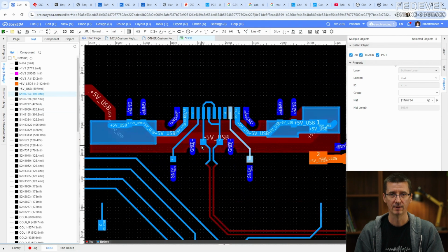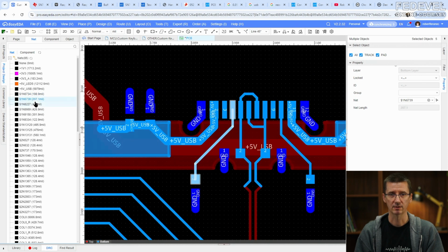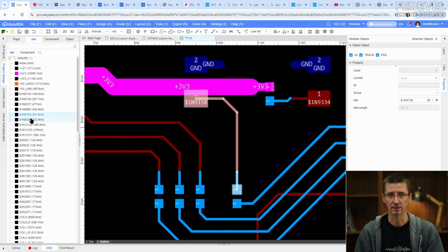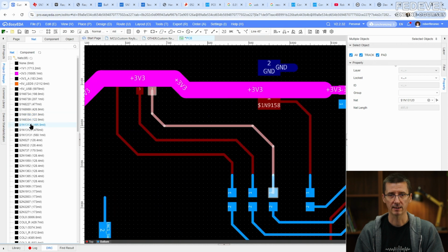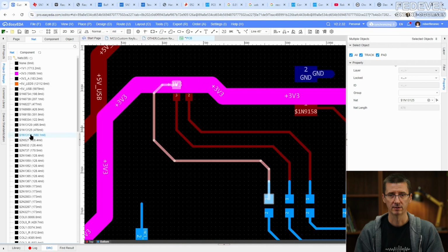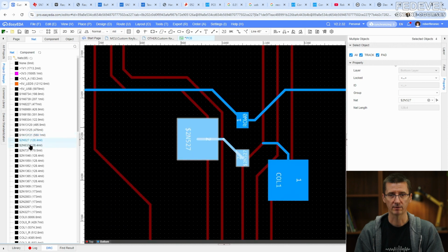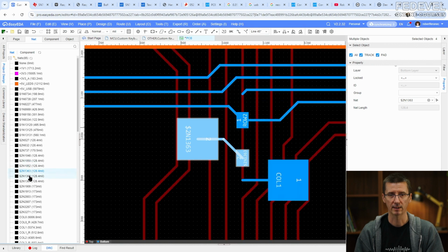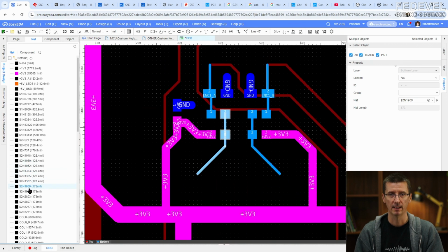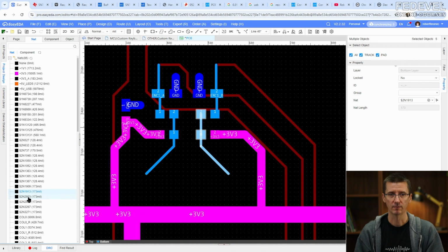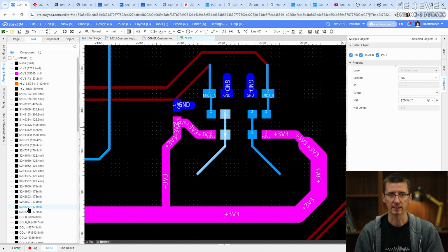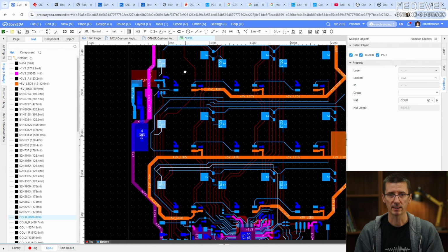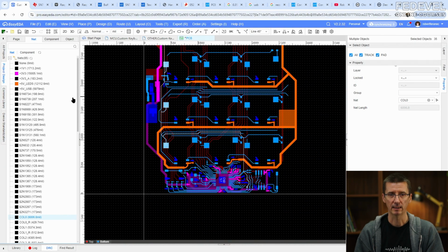Okay. Watch how these are routed. So these are connecting the 5.1K. These are the other nets. Not very important nets. Looks good. Everything looks good. I always do this for every single board I design. Spend time double checking this.